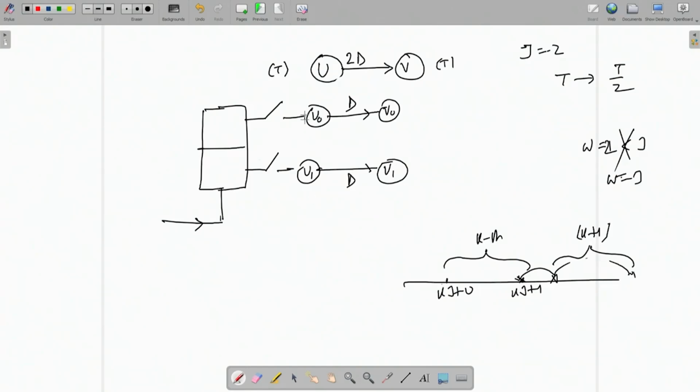So now both these edges have a critical path. I mean, this system has critical path t only, not 2t, because this edge also has a delay, and this one also has a delay. So the computation times of the 2 nodes, t and t, do not get added. So the critical path remains t. The system can jolly well work at a clock period of t. So if it is t, it will be t by 2. So you see, just by changing the retiming before going into unfolding, we can get our desired result.